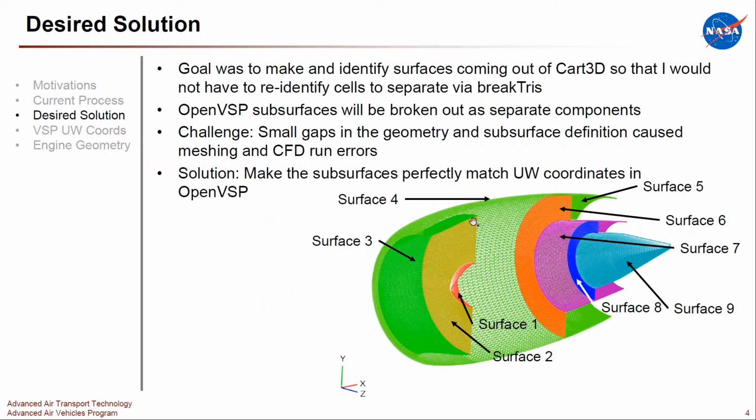This inner surface here is actually a separate surface. So if you're doing your drag bookkeeping, the engine makers typically count this towards their ram drag, whereas the external nacelle drag gets bookkept with the airframe typically. Same thing with the inner parts and so on and so forth.